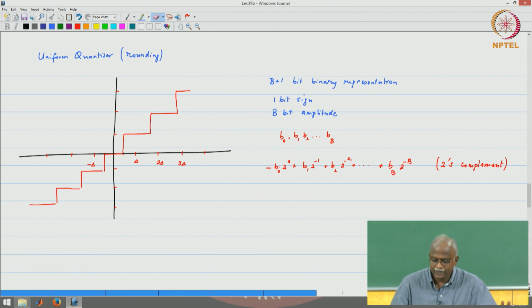Okay, so 2's complement representation, uniform levels from a range of values. Typically, if we have one level denoted as 0, then this could be a typical representation. So if I have a 3 bit representation, one of the bits is the polarity of the signal, and the remaining 2 bits are the levels. So this is how we could have a representation: 0 0 0 representing the 0 value, zeros representing the positive values. So I have level 0 1, 1 0 and 1 1.